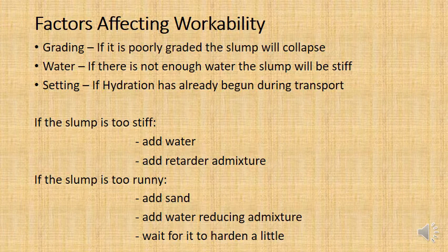One thing we can do is add water. Now, that's a little bit of a problem though. If we add more water, remember this is excess water that is not needed to react with the cement. Remember, you only need 350 mils of water to react with 1 kilogram of cement.